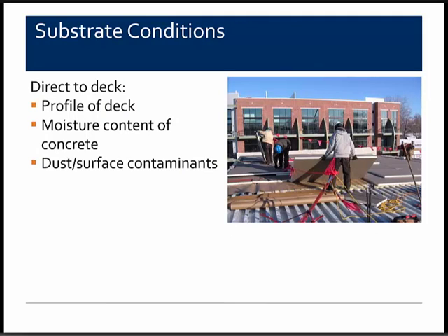Another factor that will affect adhesives is the substrate conditions to which you're adhering. If it's directly to the deck, you should consider the profile of the deck, whether there's moisture content within the concrete substrate, or flashing materials if you're leaving existing substrates in place. You also want to make sure that the substrates are dust-free. Any surface contaminants could definitely affect the bond between the substrate and the material you're trying to adhere.